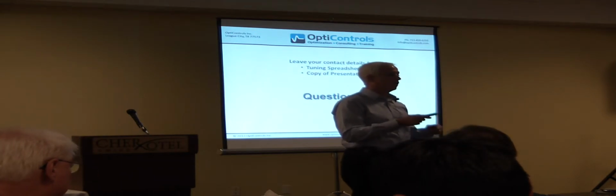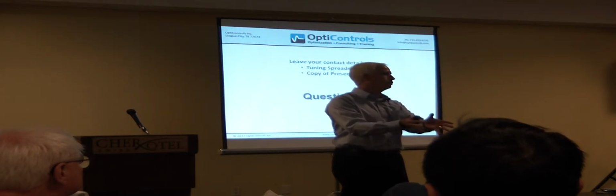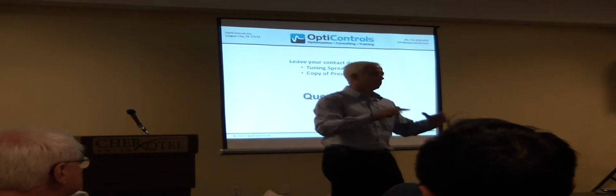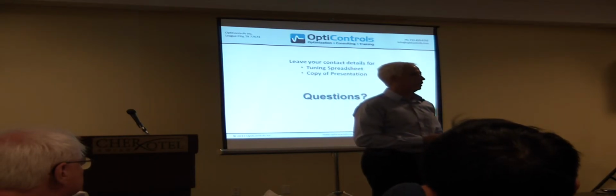Some positioners I know have a multiplier in there. So if you put a gain of 2, the number that you put in is 2, but it's got a multiplier of 15 or something in there, so it actually uses 30, which I don't know why they do it that way. So the short answer is no, I don't have any general tuning recommendations.